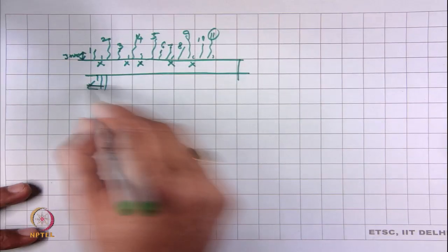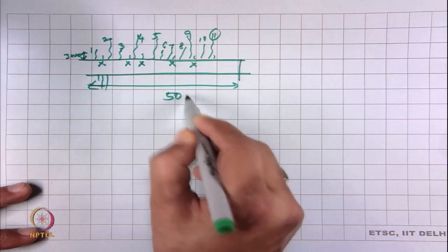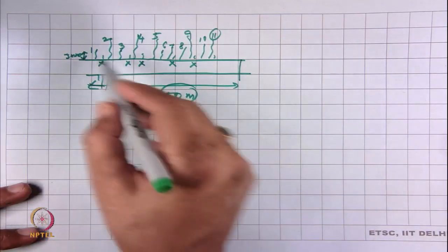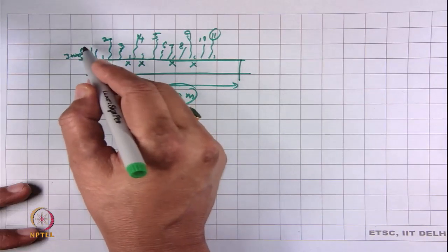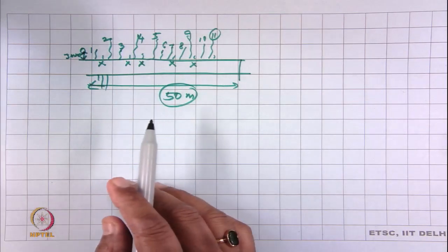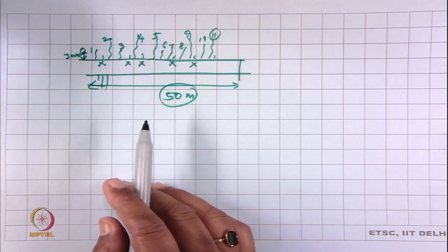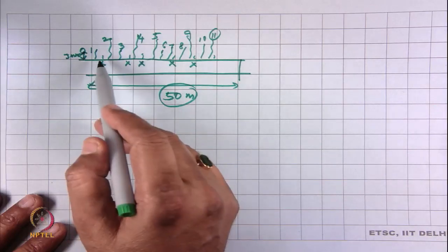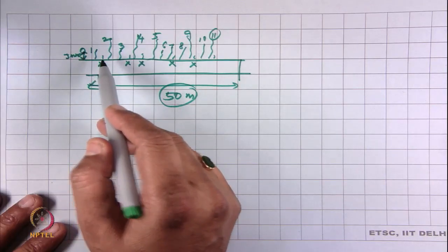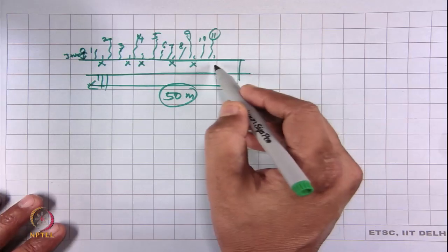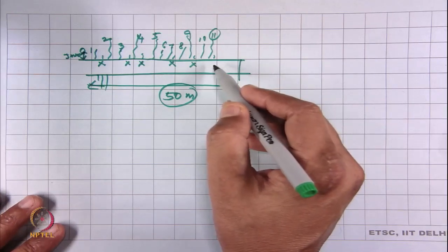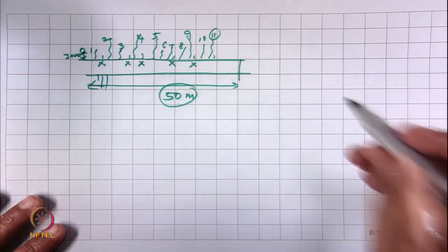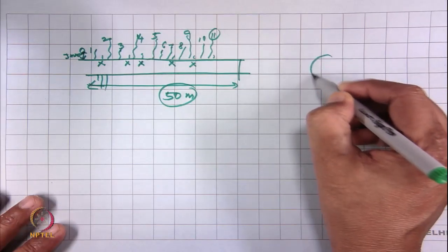Suppose 50 meter length of yarn has been passed. There will be a photo sensor, which will count. Now, the situation here is that it will only count the hairs which are beyond 3 millimeter, and yarn is not a one-dimensional or two-dimensional material, it is a 3D material, almost circular in cross section.